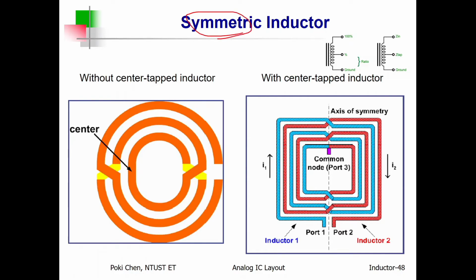According to symmetry, the more symmetry, the better the performance. Not only for other layouts, even for the inductor. Again, the more symmetry, the better the performance. You need to make it by yourself. For example, this is a center tap inductor, a circular inductor. If you cut it through the middle, it is symmetric between the first terminal and the second terminal. I promise you, with such a symmetric layout pattern, the performance will be better than the asymmetric one.